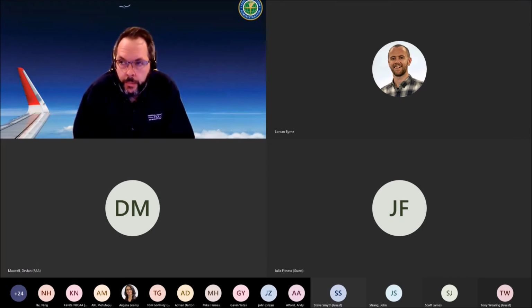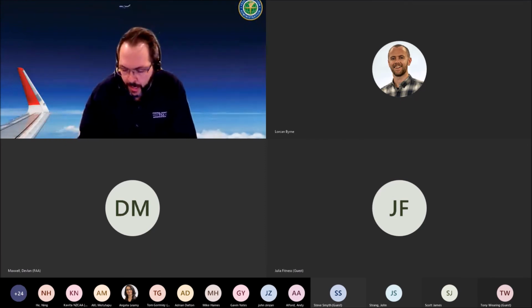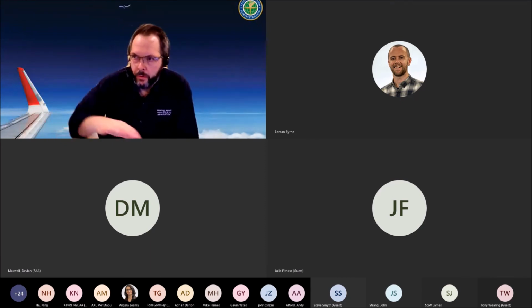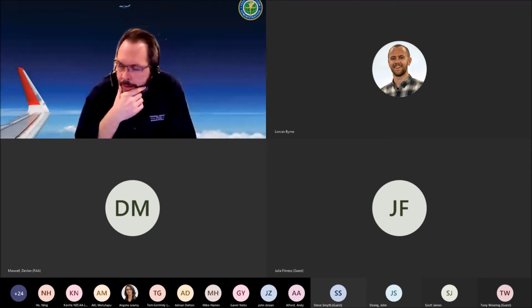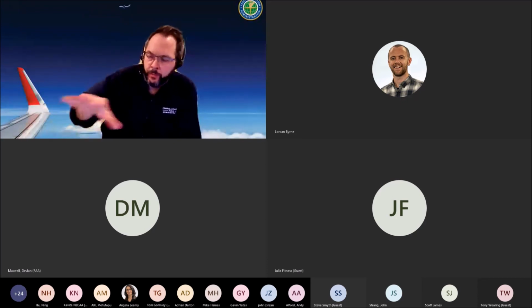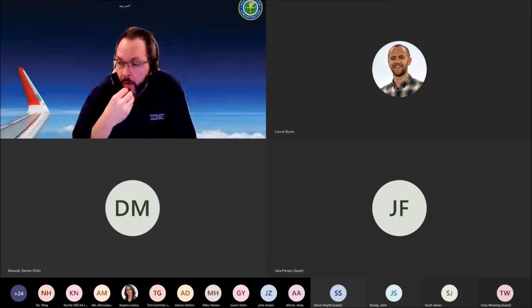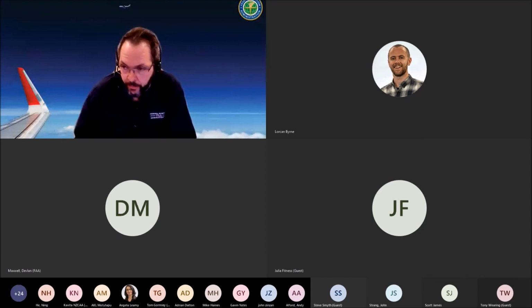We have an operational evaluation going on in the Caribbean, where Miami Center performs air traffic control for the Caribbean islands off to the east of Florida, and we have a service volume of space-based ADS-B that we're experimenting with right now. And what we find is that the update rate of the space-based ADS-B is really not sufficient for a number of reasons. We're not getting updates frequently enough to do 5-mile separation in that region because of diversity.